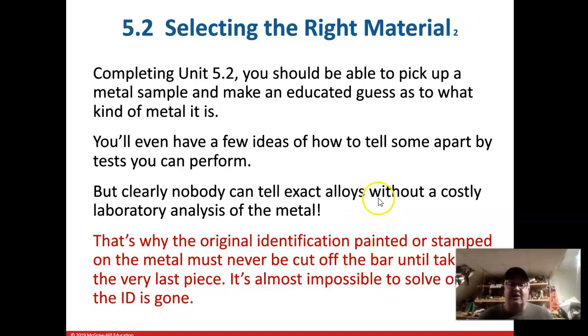As you take a look at it, there are a couple of things that you will probably need to be aware of. In terms of material, usually there is something we call a heat code. And generally there is some color coding that goes on depending on which manufacturer you're buying it from, whether it's hot rolled steel or tool steel or carbon, low carbon, high carbon.